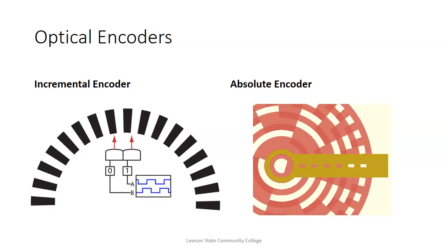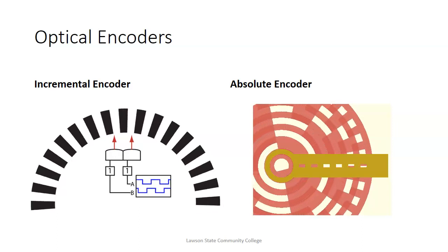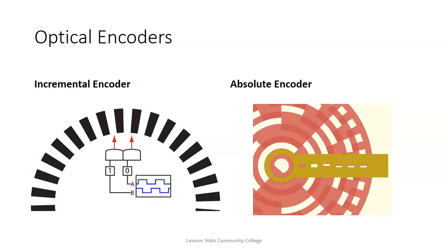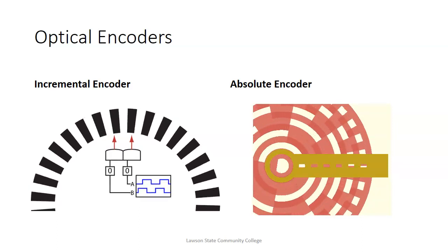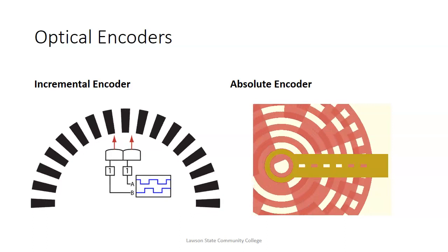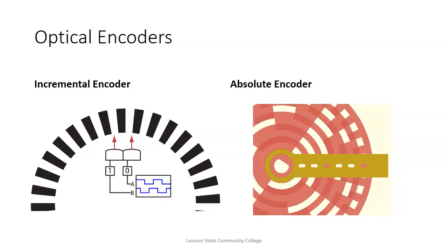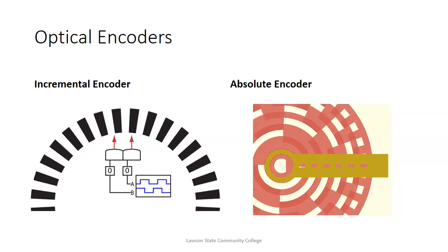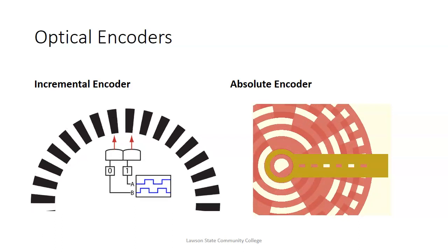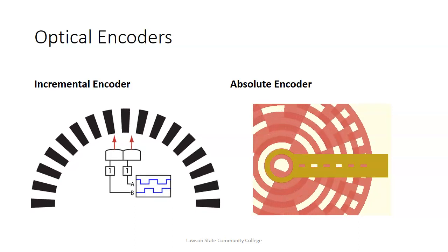No, what you do is you usually hit e-stop, but even on a robot, when you hit e-stop, it does not remove power from the... It usually energizes the brake. So what you do is you change the batteries. You change the batteries with power on.